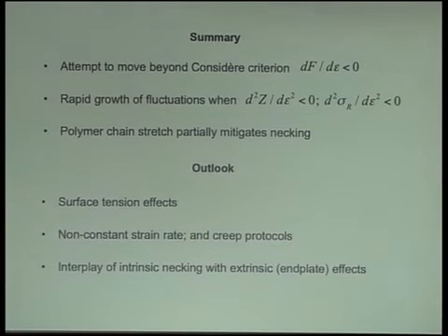Okay, so what I've tried to do is move us beyond this Considère criterion, and we've seen that there's a rapid growth of fluctuations in the regime of downward curvature in the stress as a function of time. I didn't have time to talk in detail about the fact that polymer chain stretch, as in the Oldroyd-B model, for example, mitigates necking.